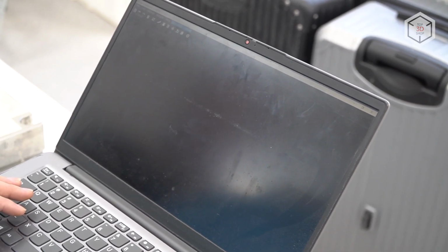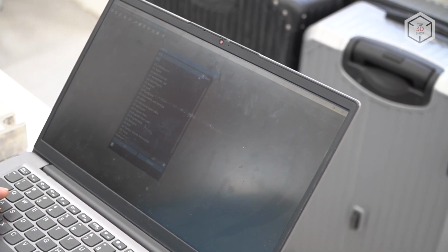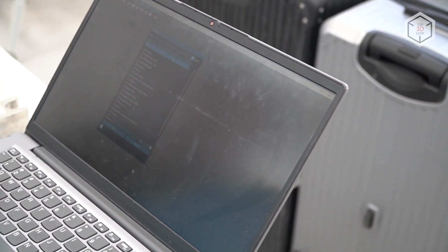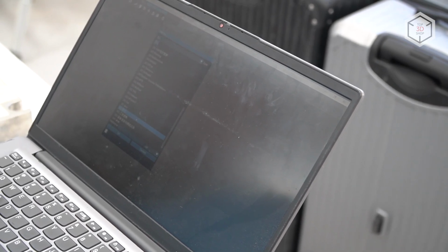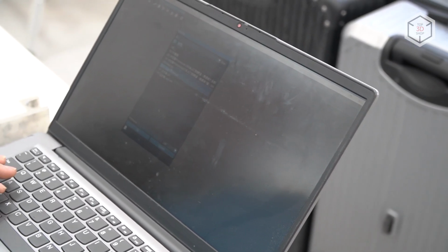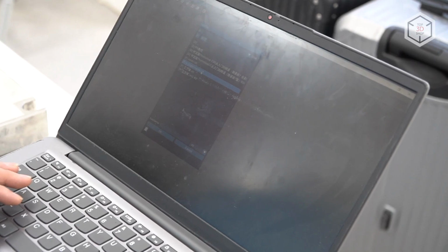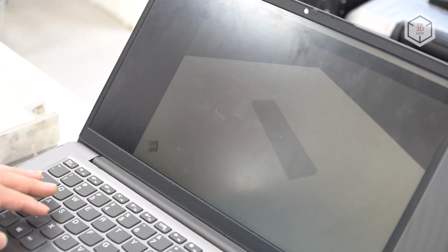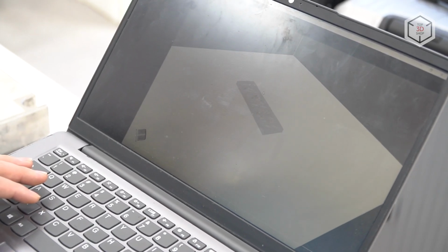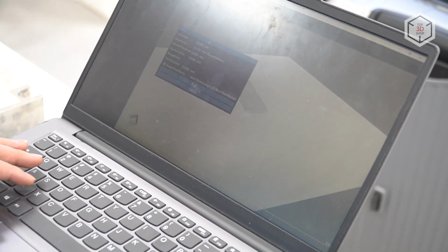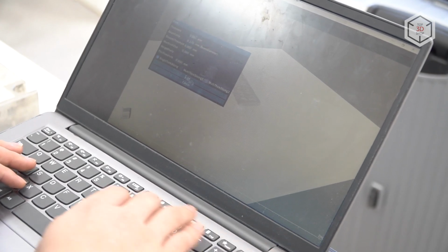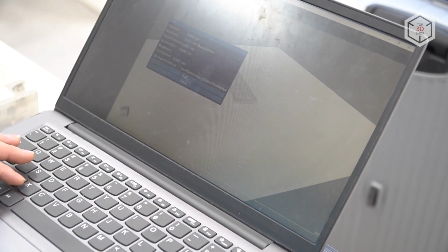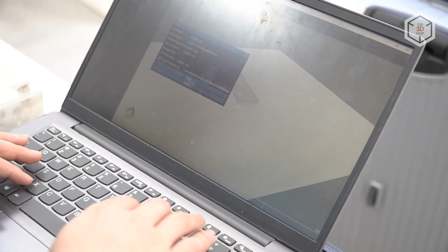So first of all, we choose the equipment which we're using. In our case, this is the HBD 350. So we choose the file which we've just sliced. And the next step for us is to set the path for the laser. We'll use the thickness of 50 microns for printing.